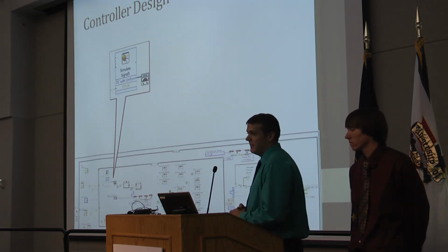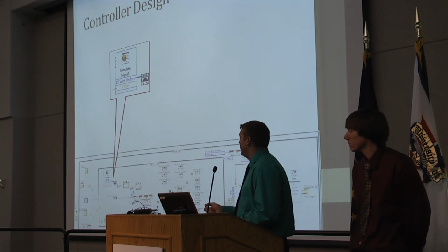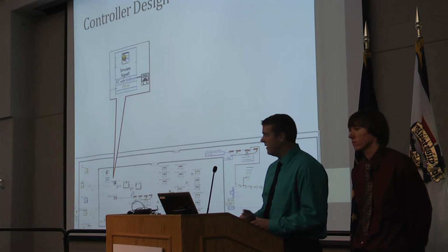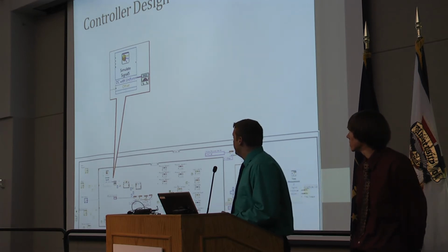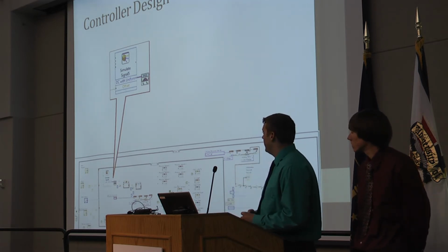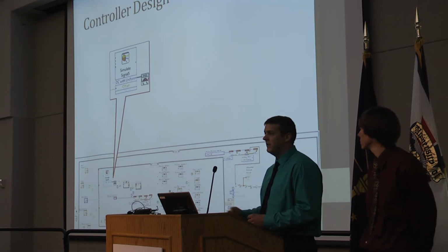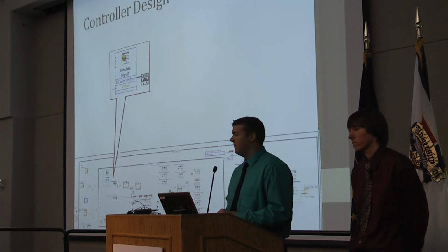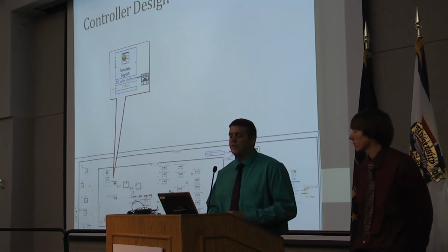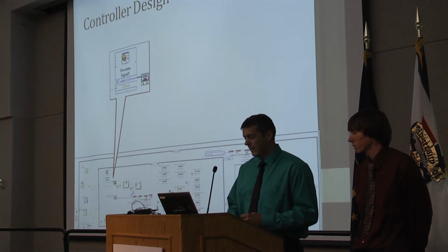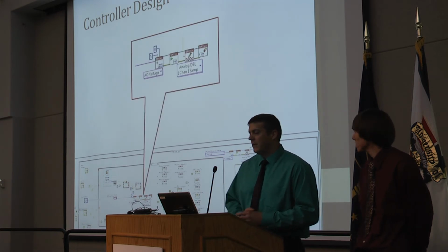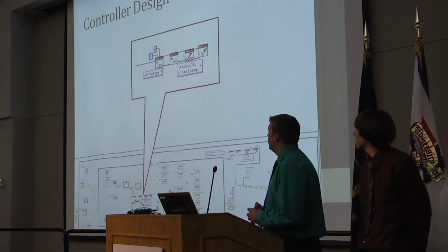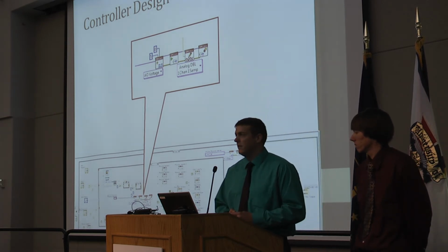After the user inputs this data, it then goes to a block like this, which simulates the signal and generates the signal to send. And this is just a block to generate a constant signal. And you can see the only parameter that's being changed is the offset. So after the signal is generated, it's sent to our compensator. And then from our compensator, it goes through 2 checks to make sure that the voltage is in between 0 volts and 5 volts, which were the range of voltages that this motor could operate within. So once the voltage goes through those checks, it goes to these 4 blocks, and these 4 blocks send the voltage as an output to the NI interface and then to the pump.